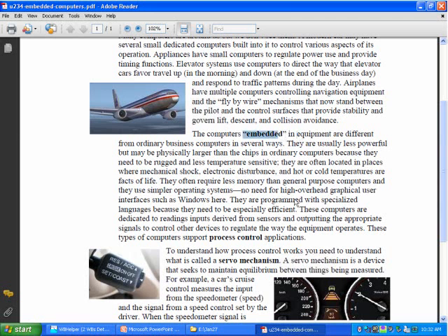In fact, I'll give you a little other information about fly-by-wire. Because it's so critical that the computers operate properly, the real requirement that's imposed is that 3 computers are used. And the computers have to be programmed in different languages and manufactured by different vendors. And the 3 computers then are all processing the same information, and another computer takes a look and compares what they're saying.